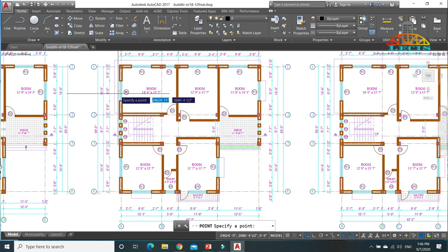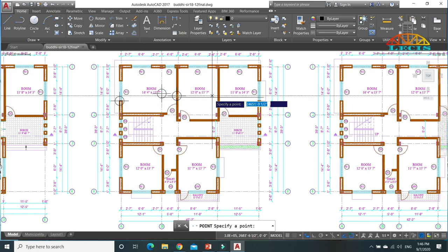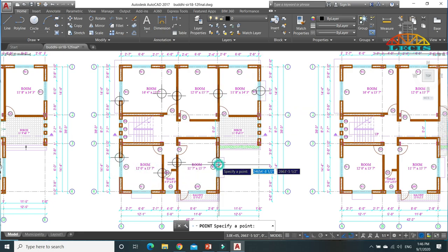And one will be this beam. This beam has the span length of 14 feet 4 inch. Similarly this. So the beams represented by this circle represent the critical beam. Now we should consider another thing. The another thing is that that beam will be the critical beam which has the longest spans and which takes the maximum load.